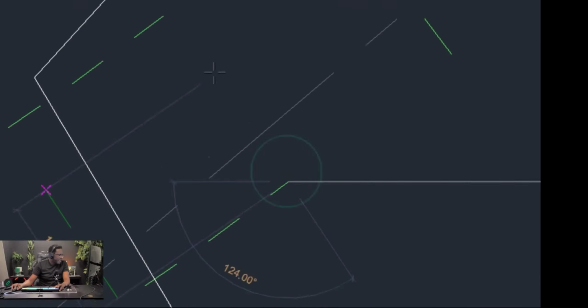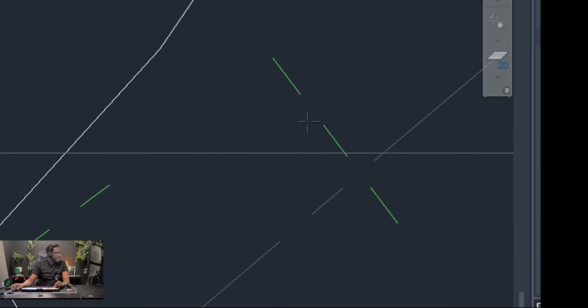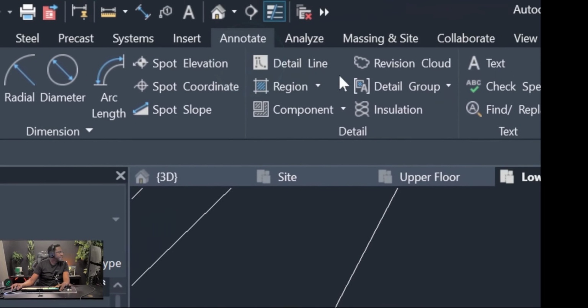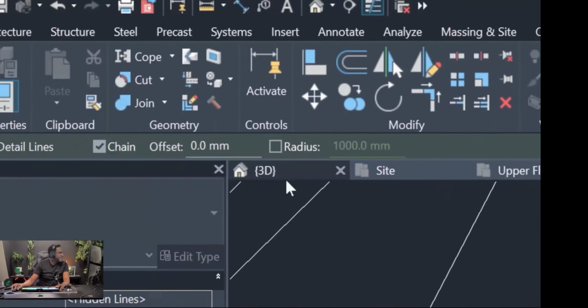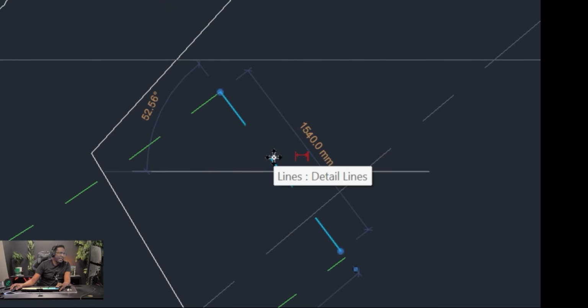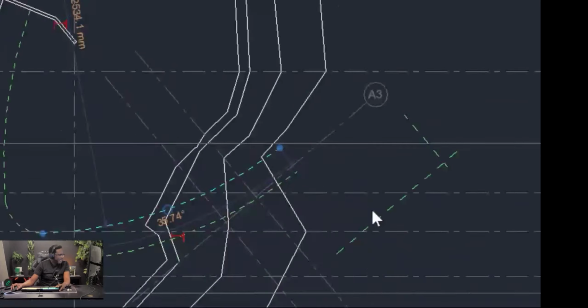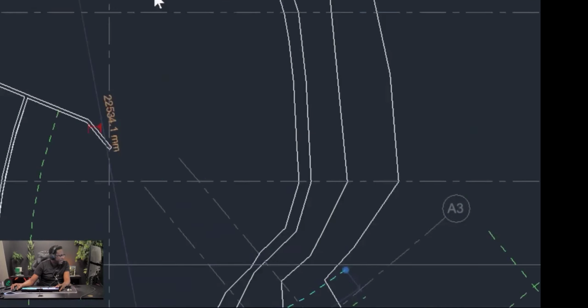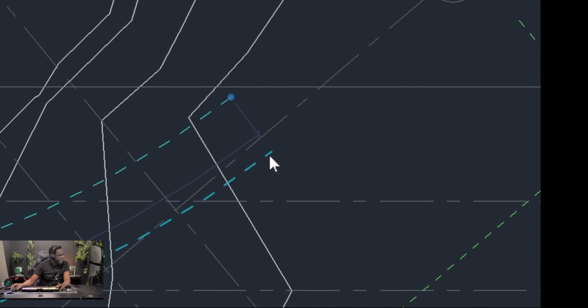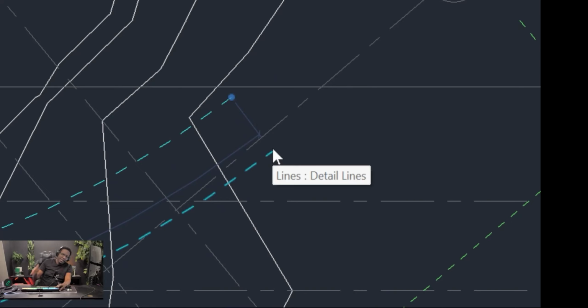To be as accurate as possible, we can't just draw a line from here to here. This is offsetting, right? So for example, if we go here and we draw a line from here to here, technically this may not end up being correct. So don't do that. Because this is a curve, it has a center point, which is somewhere here. And the idea is to draw that end line, you need to draw it from the center point to where it hits the furthest line in order for you to get an accurate end line. That's going to end up being our tread line. Because it's on a curve, you have to go according to that diameter.